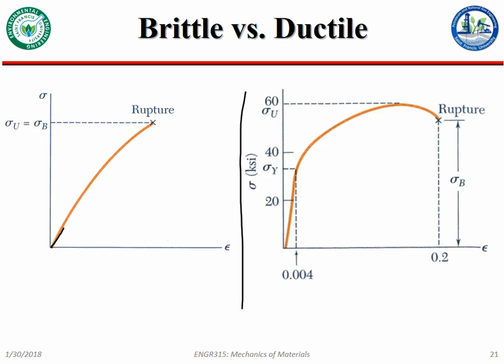It's something where stress will build, stress will build, stress will build, but you won't really know that it's building that much because it's not straining by a whole lot, and it never really reaches a discernible yield point. Its yield strength is very, very close to its ultimate strength. So when it fails, it fails catastrophically. That's a brittle material.